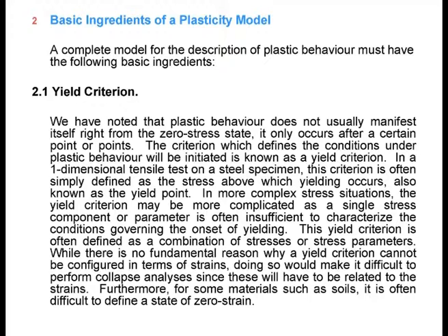You realize that the plastic behavior does not start from a zero stress state. Typically, it doesn't. It needs a certain stress level to, in a sense, activate that plasticity. So you need to be able to say, okay, at which stress level, or above which stress level, do I get plasticity? You know what I mean? Above which stress level would I start to get plasticity? Now that is a criterion.